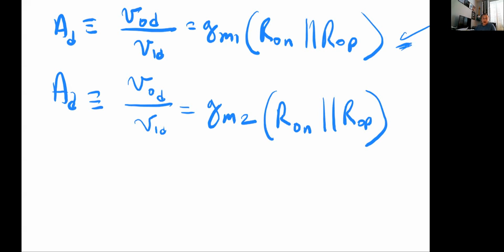So the next thing that I want to talk about is common mode rejection. If I have a differential amplifier, what I want to amplify is the differential input. But this differential input is riding on a common mode voltage that I have defined. And if there are fluctuations in this common mode voltage, I don't want to see it reflected at the output. It's common.